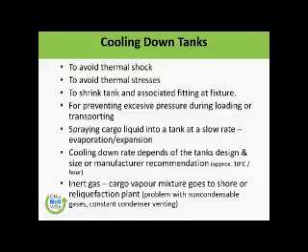Cooling down rate depends on the tank design and the size, and the manufacturer's recommendation. Mostly, as a rule of thumb, the cooling down should be reasonably slow, to avoid the thermal shock or thermal stresses. They say it is approximately 10 degrees centigrade per hour, every hour. But in some of the bullet tanks and that kind of tanks, you can do maybe 30-40 degrees per hour. So it again depends on the construction of the tank.